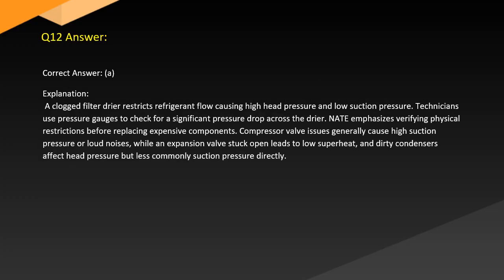Answer. Correct answer: A. Explanation. A clogged filter dryer restricts refrigerant flow, causing high head pressure and low suction pressure. Technicians use pressure gauges to check for a significant pressure drop across the dryer. NATE emphasizes verifying physical restrictions before replacing expensive components.